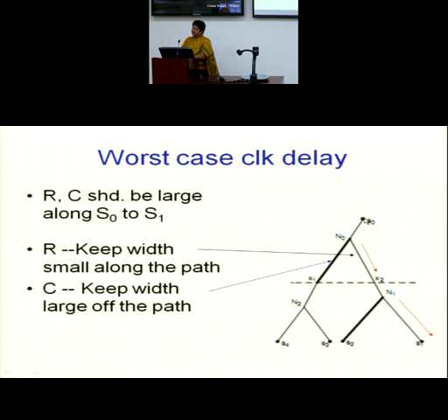Now if I am computing the delay from S0 to S1, and I am also computing the delay from S0 to S2, my skew is the difference in the clock arrival between these 2 points. I will repeat this for the S1, S2 pair, S1, S3 pair, S1, S4 pair, then the S2, S3 pair, S2, S4 pair. I will keep on doing this, because every pair should have the skew within bound. I am not talking about buffers here. It is simply the wires I am looking at. Still it is a TSW I am looking at.